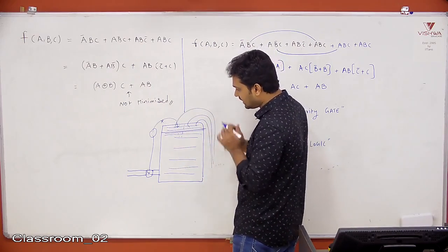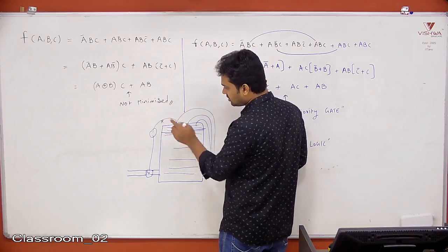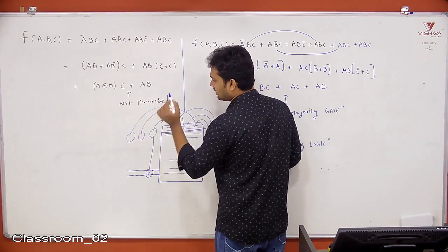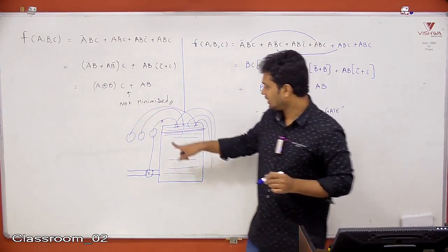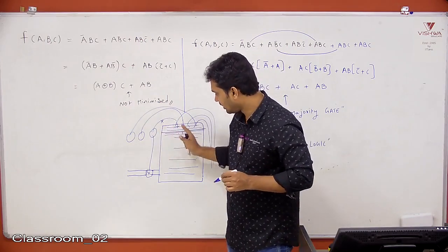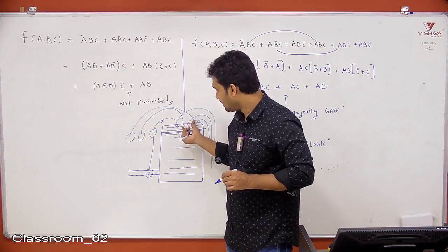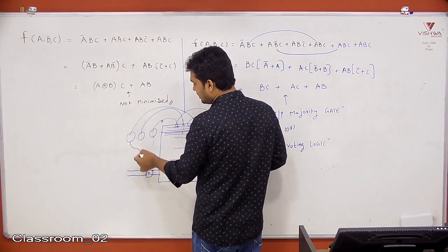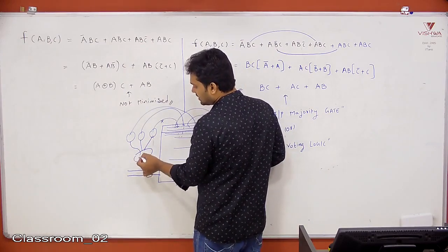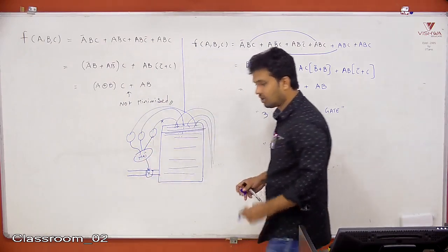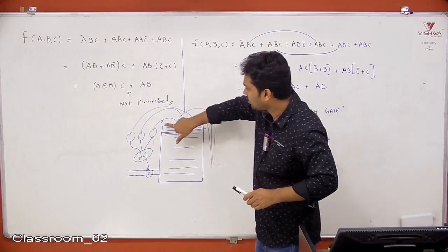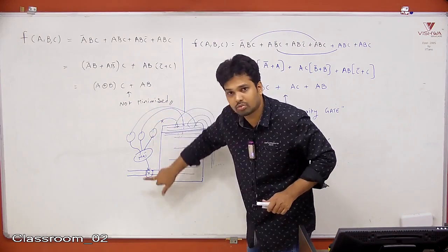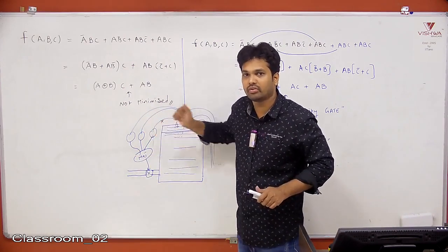So, if it is a critical application in industry, they never rely on a single device. They will take the same device again and again. They will take 3 switches or 3 transducers. In place of 1 reading, they will take 3 readings. And these 3 readings, they will give to this kind of majority gate. Then what is the assumption? Sir, one may be going faulty, but the remaining 2 are 1s, your output will be 1. Remaining 2 are 0, your output will be 0. Accordingly, it will on or off your valve.